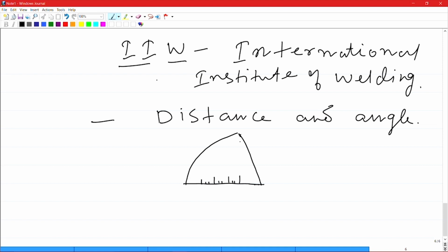Similarly, on this surface also you would have these angle scales. So, depending on what is the angle that you have, either this surface or this surface can be chosen when you are calibrating the transducer for the angle. Okay. Right. So, these are the two types of blocks that you have available for calibrating the angle for a particular ultrasonic transducer.